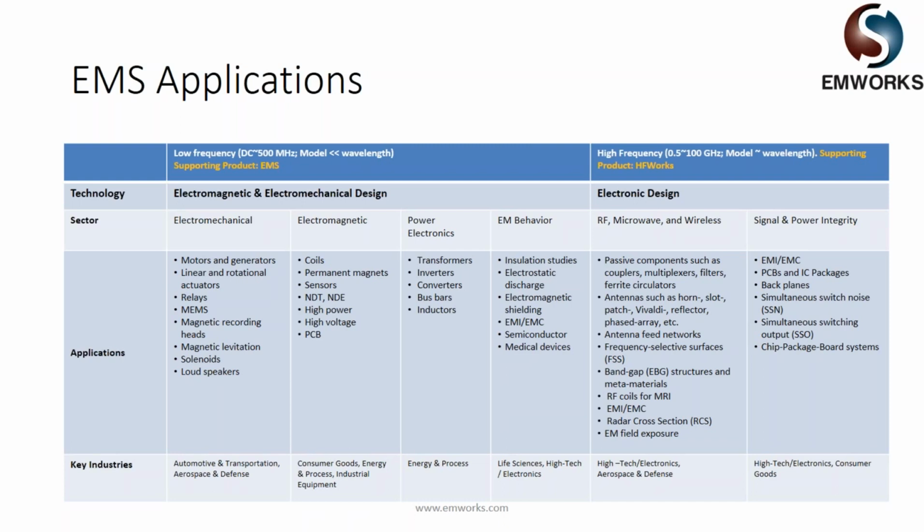Now there are several different application areas in this EMS product. First of all, one can simulate electromechanical devices like solenoids, motors, generators, maglevs, magnetic levitation, speakers, magnetic recording devices, all kinds of devices that work on the principle of magnets, magnetic field and magnetic energy.